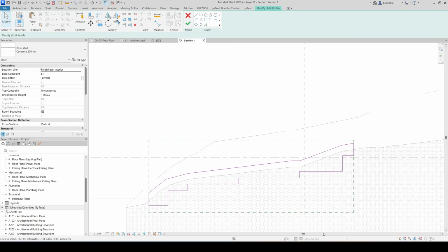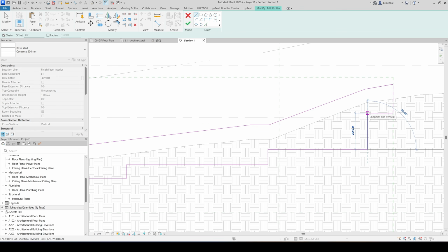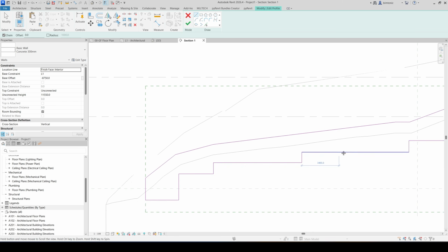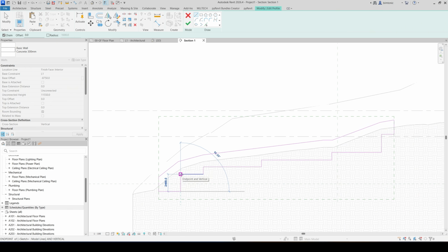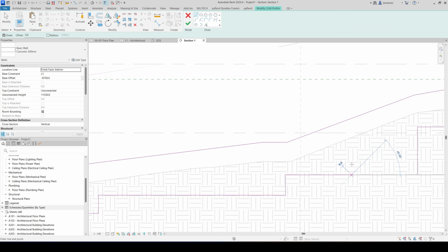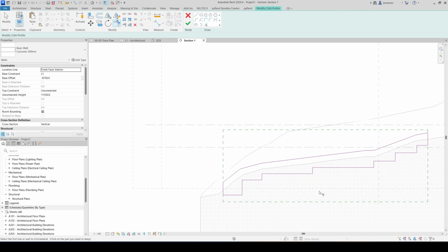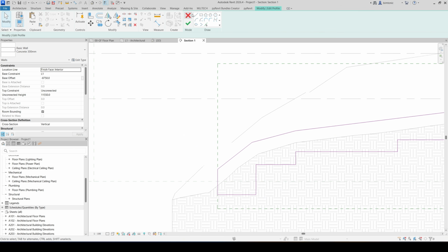I just trim that. So now a couple of these seem a little bit too deep, like for example this is 2.5 meters deep and this is 2.4 meters deep. So that means maybe we should split this part in half. So here in the half of this line, half of this value, I will also offset by 700 millimeters, so I have a little bit less sharp steps. So I trim them once again, and now this seems a little bit better. And I will do the same here.